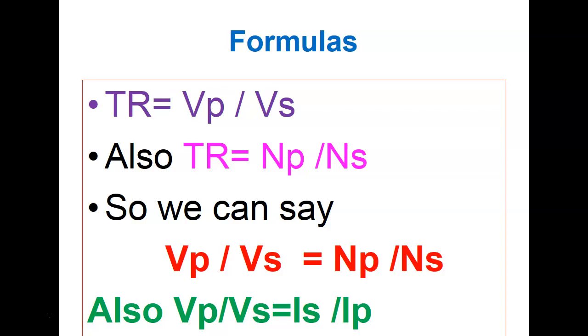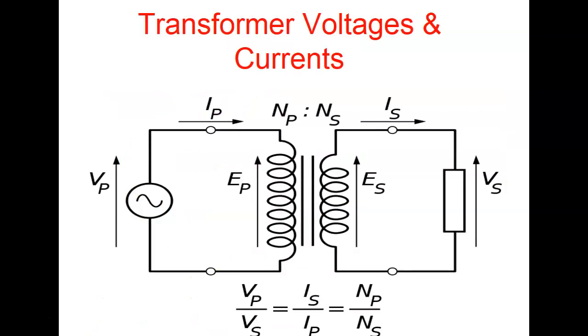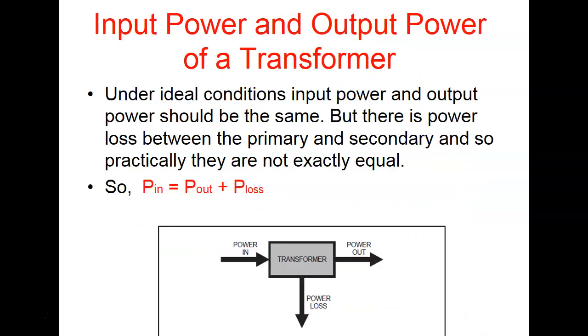Motors do the same thing, guys. Motors use that magnetic wire, and the biggest thing they have is the vibration and the insulation rubbing against each other. And then you have shorted windings inside there. And why is the insulation so thin? Because they got to get really good magnetic coupling between the wires, right? So we call it magnetic wire. So all this is just the same thing. We're going to go through this. So everybody okay at that, right?